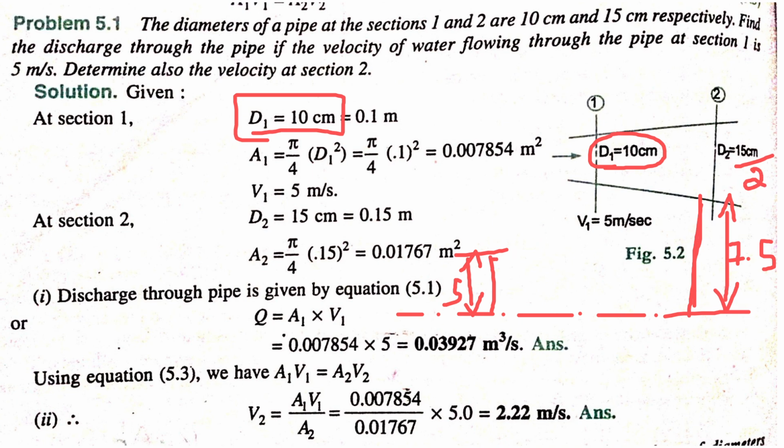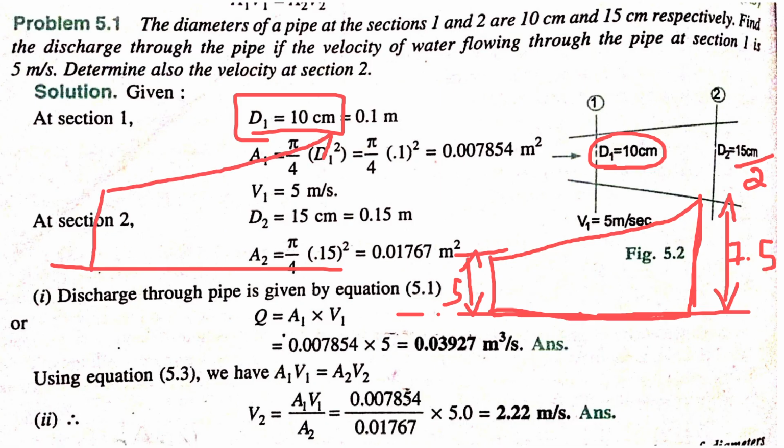Then I will join these two vertical lines with an inclined line. Then I will join these two vertical lines at the bottom with a horizontal line. This is how I can finish the first part of my modeling. Later I try to revolve this part. If you see, this is my first sketching. I try to revolve this one around the x-axis such that I will get my three-dimensional or 3D model. So I will do it now.